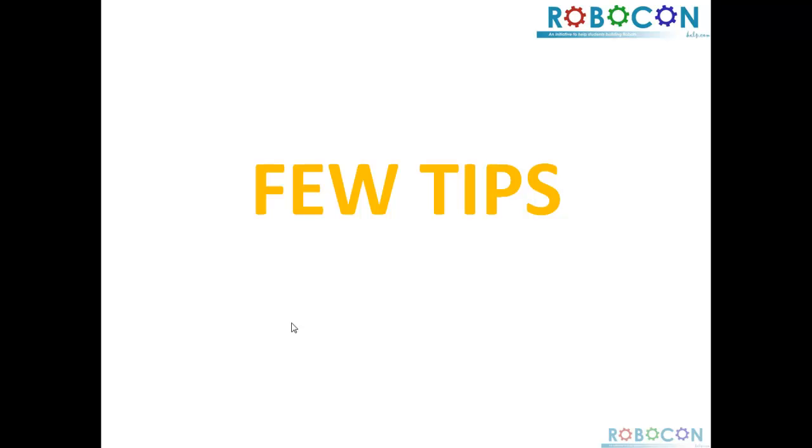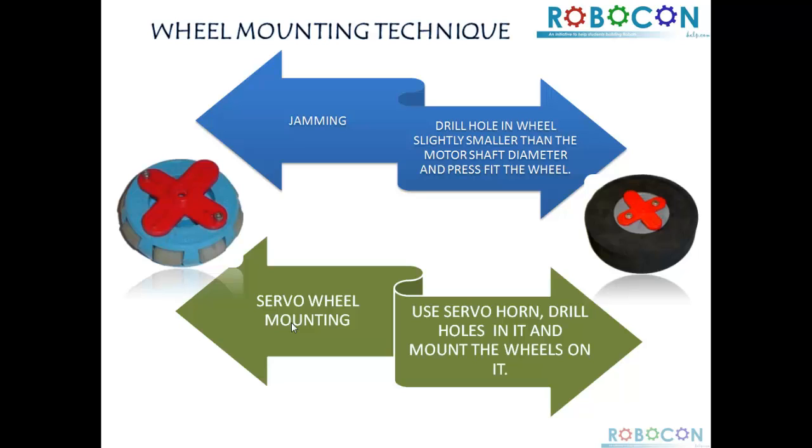We have a few tips for people who are looking forward to making a wheeled robot. Just like jamming, generally people have a tendency to drill a hole in the wheel slightly smaller than the motor shaft and press fit.